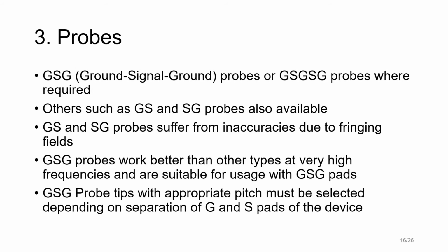Also, to reduce the capacitance between the ground and the signal probes, another ground can be added next to the signal probe, thus forming a GSG structure. This has the effect of reducing the capacitance, but also the amount of fringing of field which happens to the chuck. Another drawback of the GS probe is that one less ground probe means less shielding, resulting in crosstalk problems.